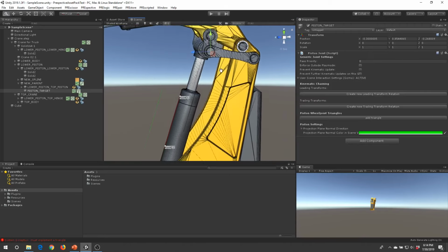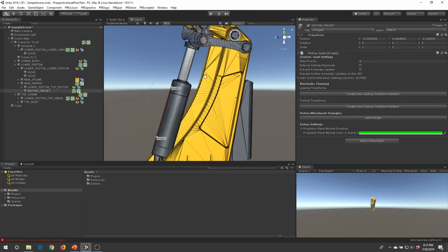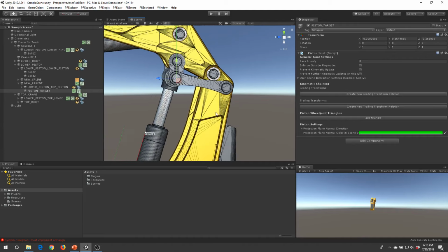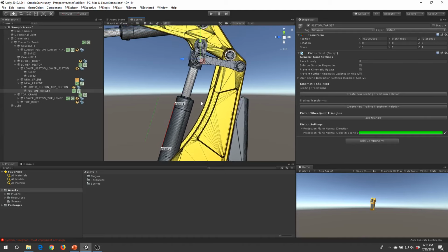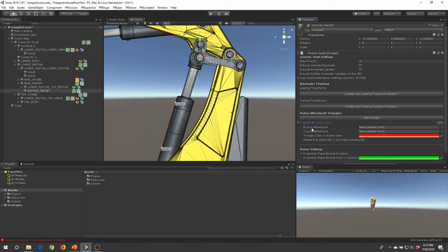And the piston joint actually requires you to do a couple of things. First off, it needs you to add triangles. Like it says, must implement a triangle. So these triangles are always based around a singular arm towards a wheel joint that is either rotary and static in length, or static in position and static in length, or dynamic in length with or without a prismatic joint. So let's set that up. So let's add a triangle, and now it expects me to add in a wheel joint and another wheel joint.